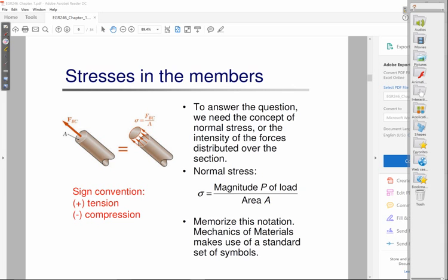Normal stress is not a scalar quantity. That's the big difference. It's kind of like the difference between speed and velocity. Speed is simply the magnitude of your velocity. Velocity has a direction, speed does not. It's the same thing when it comes to normal stress. Pressure has no direction to it. When we talked about pressure on the inside of that balloon, all we know is that it's pushing perpendicular to the wall of the balloon in all directions. There was no particular direction. Well, normal stress does have a direction. So look at stress as sort of the vector equivalent of a pressure.